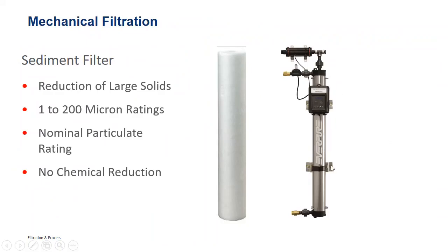So if you're looking for someone who needs viral protection, immune compromised patients, people that are rather paranoid about their drinking water, or industrial applications that may need ultra pure sediment free water, UF is a good way to go. It is backwashable and it filters down to the virus level in most cases, and it's certified to do so.